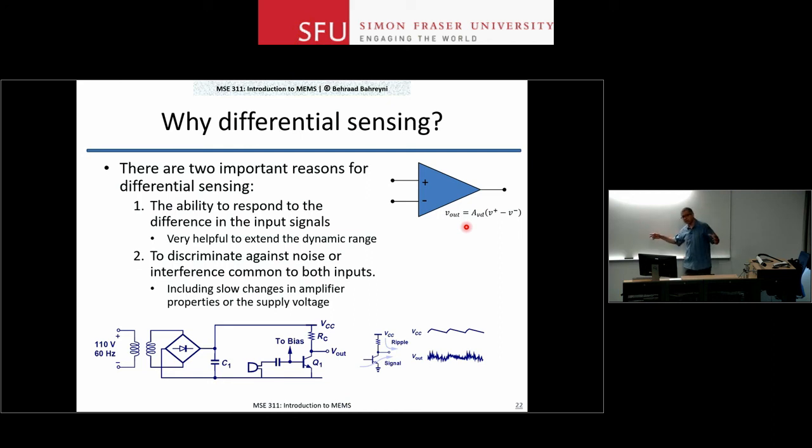If you have no other choice, what you do is create a twisted pair. You twist the two wires around each other so that the interferences start to cancel each other along the length of the wire. But at the end of the story, you will still have some interference coupled, even if you use a twisted pair. But it will be the same on both wires, as long as you keep things symmetric. If you use a differential amplifier at the end of this line, it just subtracts the common interference from both sides.